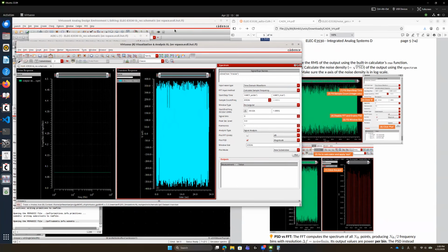Okay. And then what is this window size? So window size is that we are learning power spectral density for, how to say, the segment. So if we set this window size the same as sample count, which is the number of samples, exactly the same, then we are running FFT for entire samples. But if you set window size smaller than the number of samples used in the simulation setup, for example, as indicated here, 64, I set 64, then what happens is that